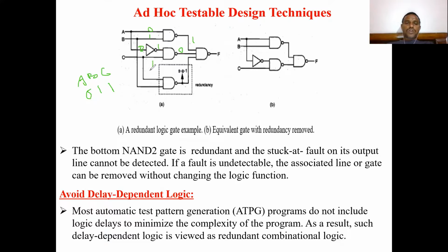Next, what we have here is 1, so here also we are getting 1. Next, B is equal to 1, so it is an AND gate and I will get 0. For the NAND gate with 1, the output is 1. The same values I apply here, where the redundant circuit is removed. The redundant gate is this one. Even if I remove this, I will see what we get.